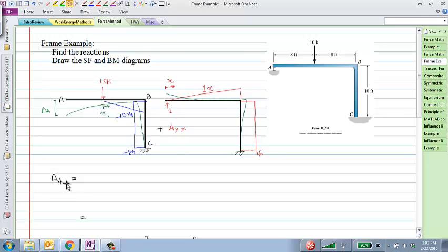So to calculate displacement at A, I would have virtual moment. So I'll write that here. And I'll set up my integral in terms of x1 actually, because the left half of this real system is really 0. So I'll use x1 and I'll write that integral as 1 times x1 plus 8. That's the virtual bending moment in this half. 1 times x1 plus 8. Hope you see that. And times the real curvature. The real curvature is just the curvature due to this part, which is minus 10 x1 divided by EI. And I integrate that dx1 from 0 to 8 feet. That's the displacement due to this component.